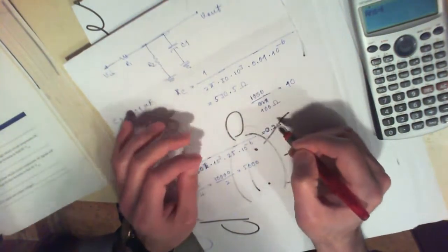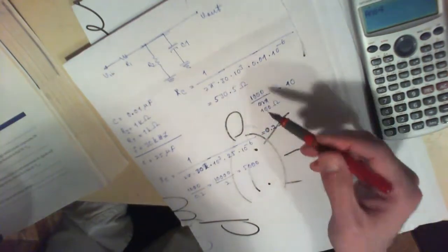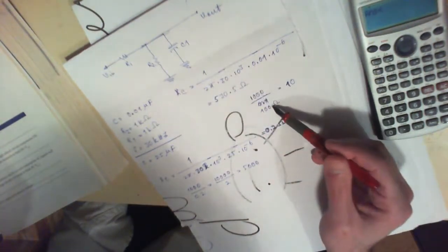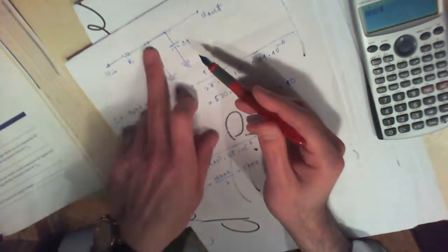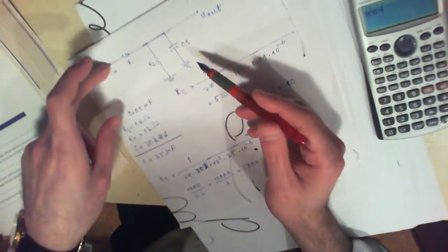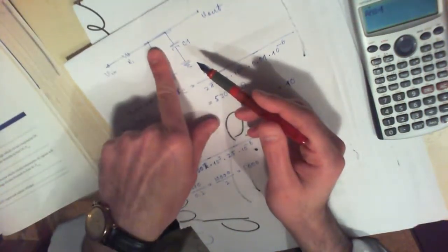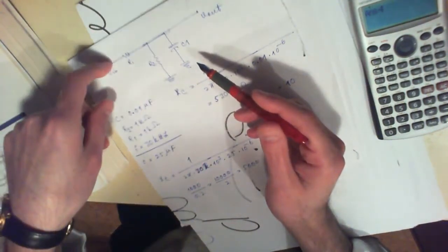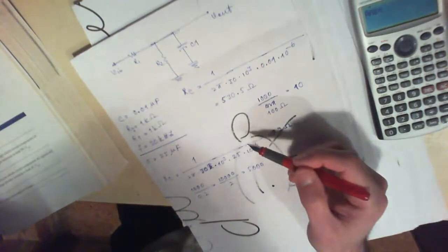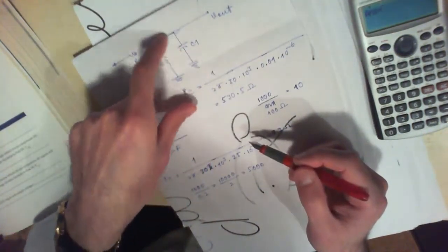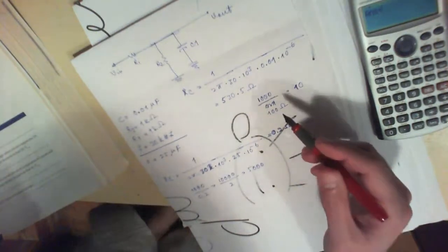So all the way up to 100 ohm reactance, if your resistor over here is 1 kilo ohm, then you could simply oversimplify, and for an AC signal, you could simply ignore this resistor, and then say that when AC comes in, it's going to simply behave like a simple low pass filter, for example. Otherwise, when